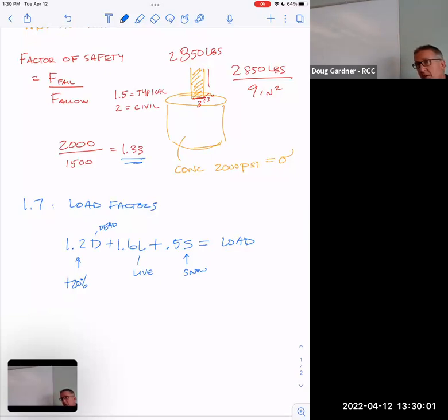Like, you have to put a bolt in the concrete that's tied. It's got a J on the bottom of it so it won't come out of the concrete. And then you bolt a piece of wood down to the top of it, and then you build the house on that wood. So that connection is kind of sketchy, because your house can just vibrate right off of the foundation, if you will. Generally speaking, your foundation is buried in the dirt, so it's not going to move with the ground, but your house can kind of vibrate off the foundation if it's not one of the codes they changed recently.